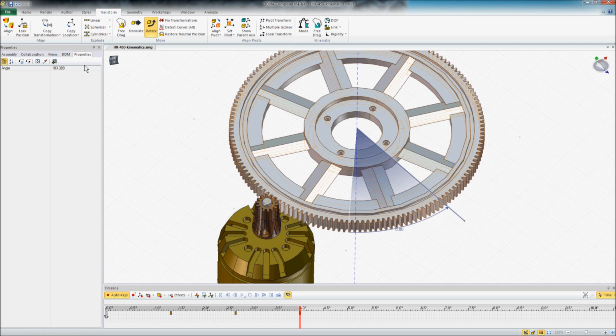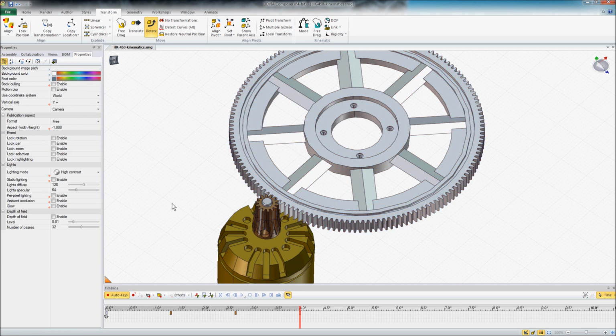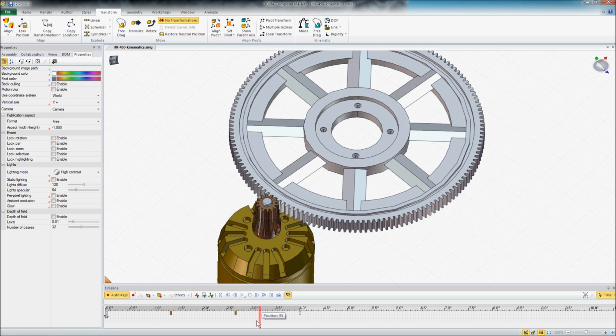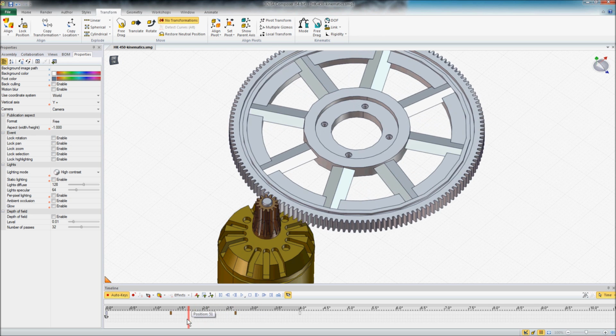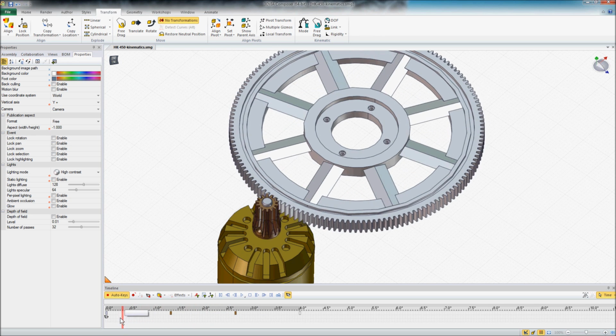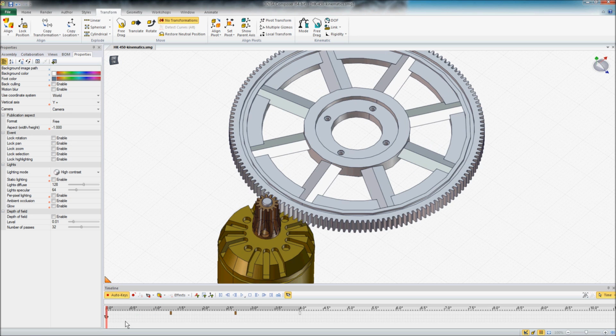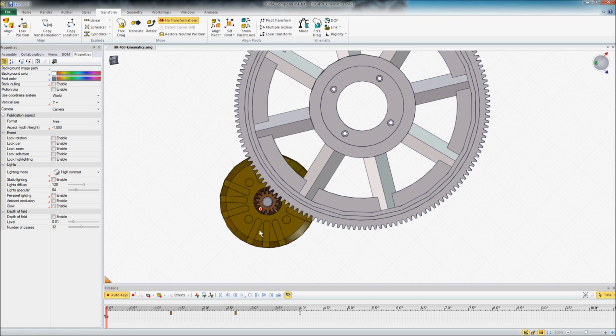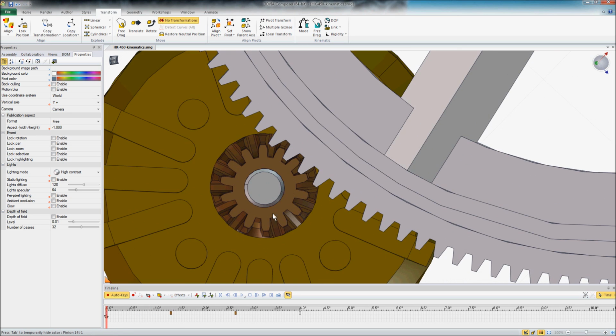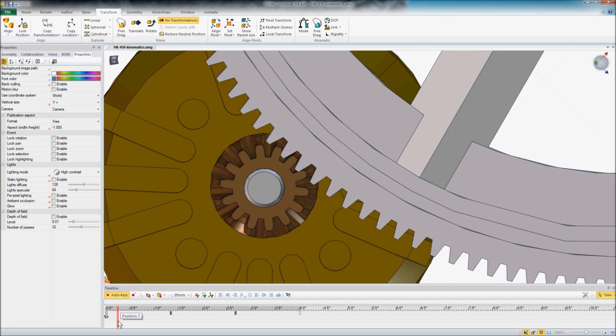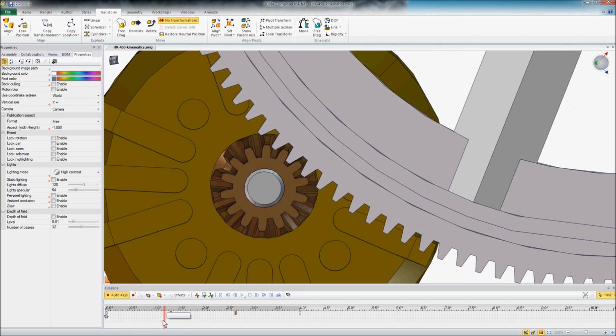But what I determined was that a negative 33.7 degree angle worked pretty well here. So we'll put that in. And now as we back up here, you can see that those teeth work pretty well and give me a pretty good result. If I rotate this around and take a close look at it from the top, I need to make sure that I turn off my camera play mode here so it doesn't change my view on me. But now as I drag this around, I can see those teeth are working pretty well together.